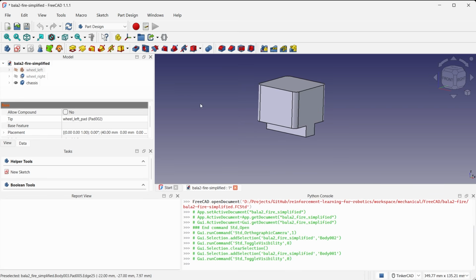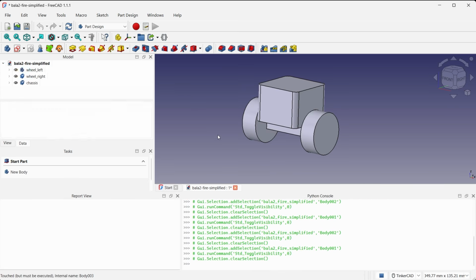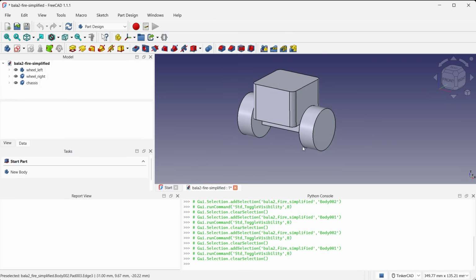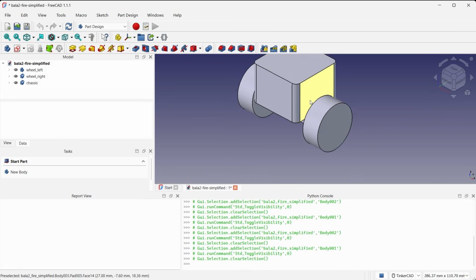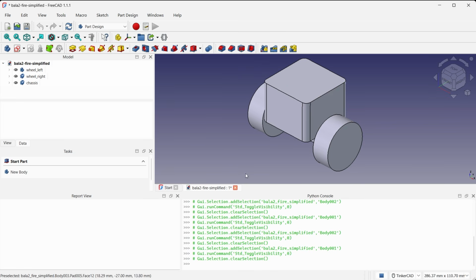It just kind of assumes it's one body. We also have the left wheel and right wheel. They are essentially the same, but I modeled them as 2 different bodies. You could probably get away with just modeling one and then duplicating that in the simulator, but I like the way this looks in the CAD program. You could spend time making this more exact and modeling it as the robot actually is, but you will find that it will increase your computational complexity during simulation and may not be worth the amount of time spent running the simulation. Also note that MuJoCo uses convex shapes to simulate contact physics.